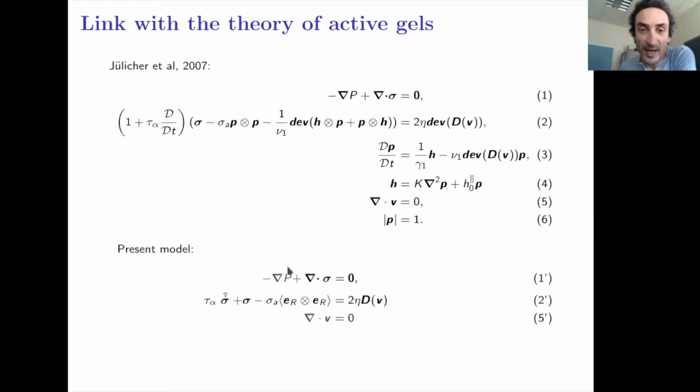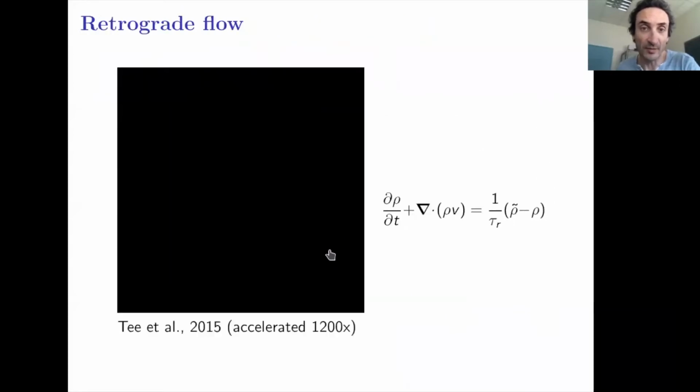So in my model, I've added here the effect of a solvent that you would often have in a model of polymeric liquids. Actually, I'll remove that and I'll explain you why very soon, and rather use a second viscosity or bulk viscosity here to prevent the divergence of V from being too large, and also because that's a usual term, although it doesn't come out of the derivation that I've shown, and that's usual also for this sort of derivations. I'll explain to you why I believe you shouldn't have incompressibility.